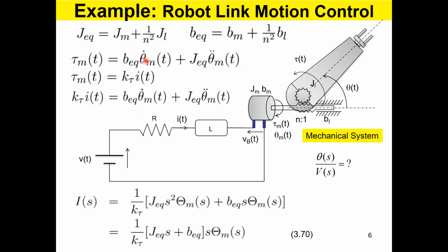Now, because of the motion, only a percentage of the torque goes in here. And because of the motion, there is a back EMF now, which was not there initially. When the motor was not running, there's no back EMF. Now it is running at some speed, there's back EMF. Therefore, this current also reduces.